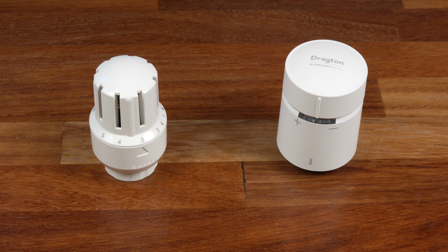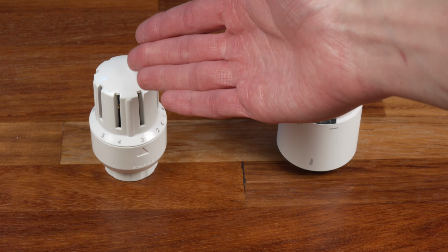With gas boilers and heat pumps, you really don't want to be overly restricting the flow through them because it will operate inefficiently. So you really shouldn't be going out and using a system like this to completely turn off radiators in rooms that you aren't using. You can maybe turn them down a tiny little bit, 1 or 2 degrees, but I wouldn't recommend turning them all completely off or setting them to really, really low temperatures. And similarly, you can always do that with a normal radiator valve.